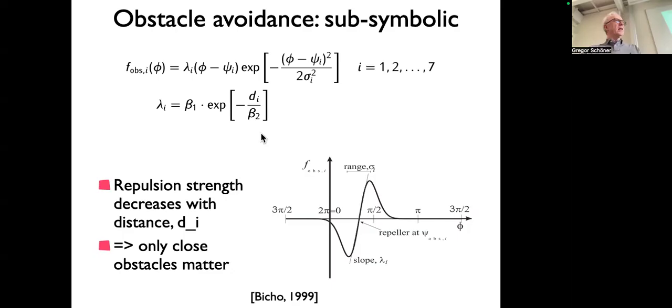We talked about time scale last week, and spatial scale is the same idea that you could sort of say over which distance does the strength decay by a fixed factor, and that would be this beta that then determines that scale. So when you sense d, then the strength here, the slope of the linear function, would be modulated in this way. And the overall strength, there's a factor in front that modulates the overall strength of the obstacle avoidance term. So that's how sensory information enters actually into this.